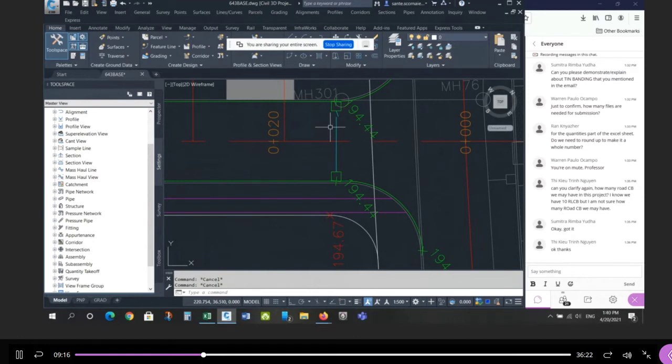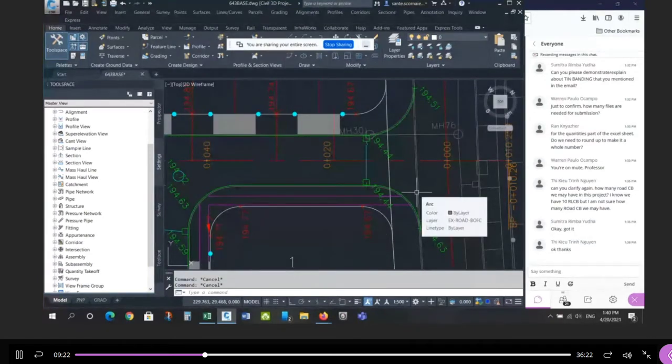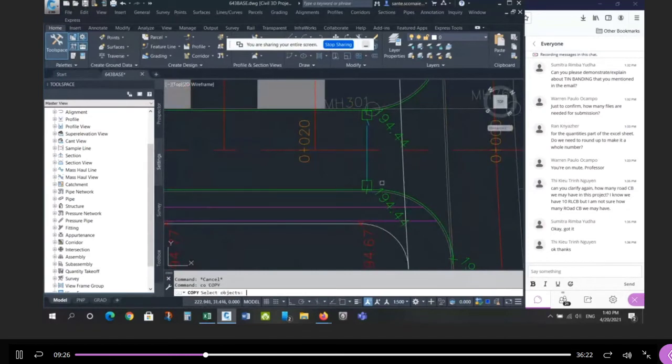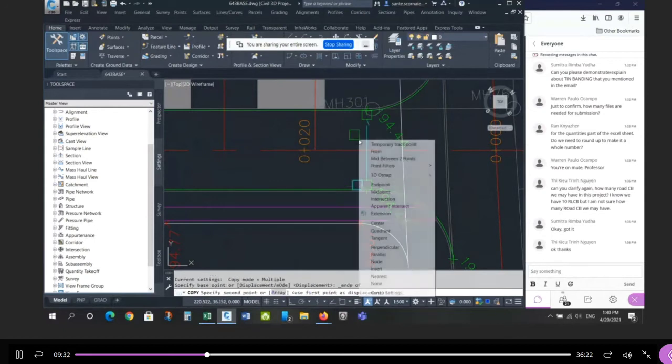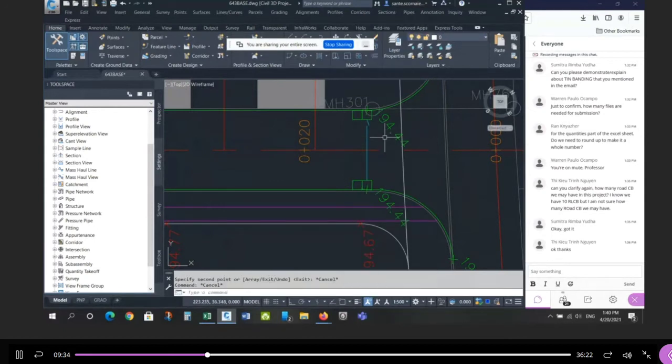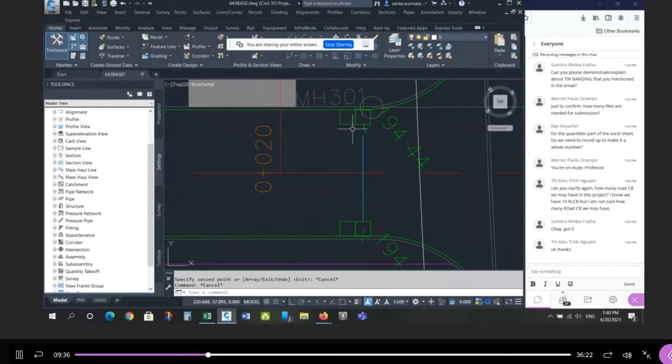Okay, so if you read the standard, it tells you where you might have to put in a double catch basin. I forget, somebody showed me, I forget the number, but if somebody wants to look it up, we can read it together. Where you need double catch basins. If you have a double catch basin, as far as cost is concerned, I would just double the cost of a single, right? So I don't have it, it's generally a little bit cheaper, but I would just say, okay, this is the same cost as 4 catch basins.